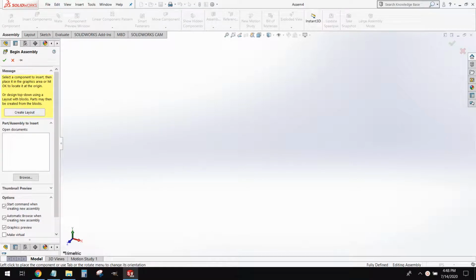Now, a couple weeks ago, we went through and we created basic assemblies in SolidWorks. And for that, we more or less let the mate tool select the proper mate. And for 90% of your mates, that's going to work just fine. You can select the two surfaces, and so long as everything's modeled properly, it's going to behave more or less like you expect it to.